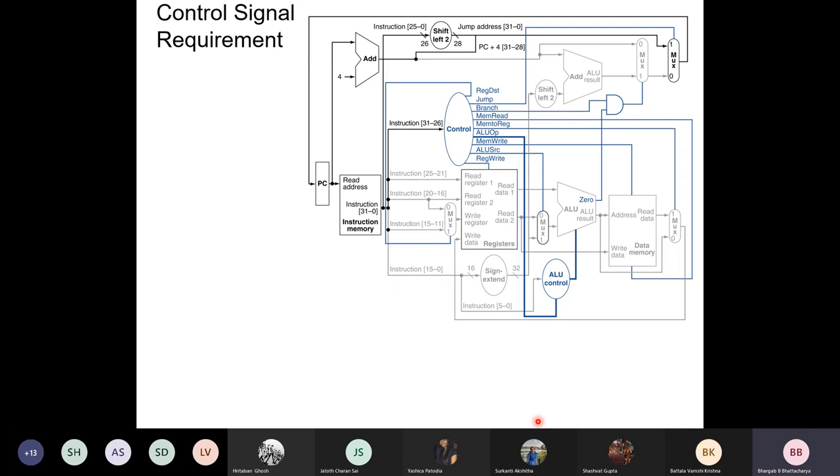Now, as we have already seen, this is the overall design we have come up with. Do you have any doubt or question here regarding the control lines or the components? This is for implementation of branch. This is for implementation of jump, and load and store are implemented here, and all these MUXes and sign extension logic, these small blocks are needed. The designer looks into the instructions and figures out that in order to execute those instructions, I need these modules and how they should be interconnected. So considering the subset of instructions we are referring to, we come up with this design.